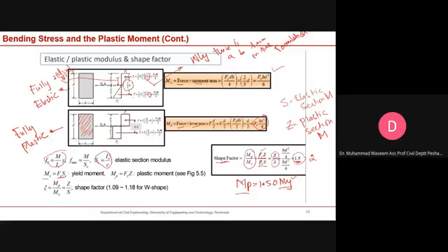Okay, Mp, which is known as the plastic moment, you can estimate with this formulation. So you have to take the ratio of these two in order to get the shape factor. So this is done here. So the Z value or S value over here, once you go for this Mp and My, you plug in these values here, so you solve for it, and at the end you will get 1.5. The shape factor for a rectangular cross section is 1.5.